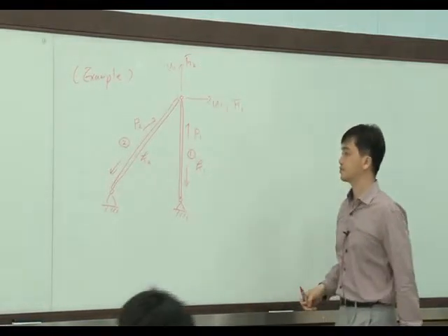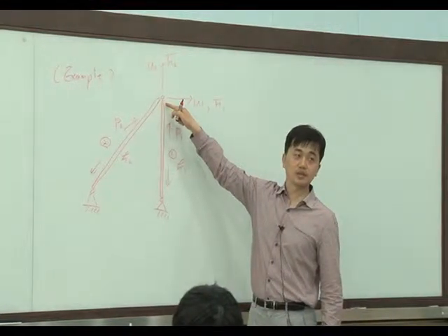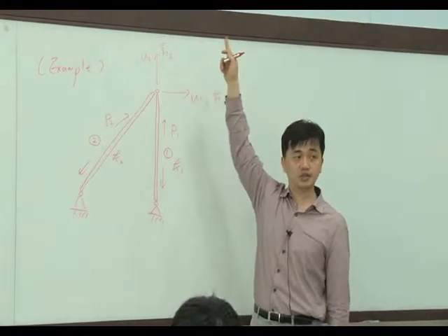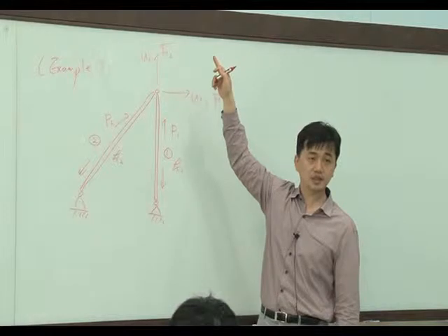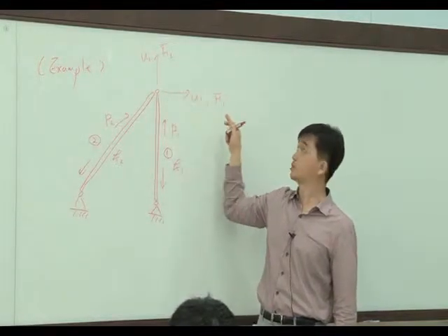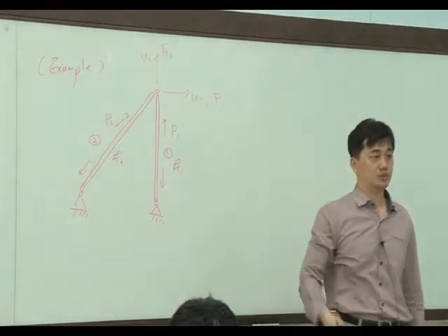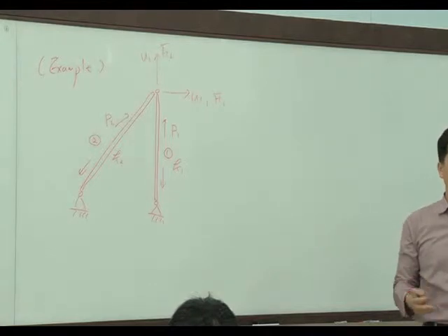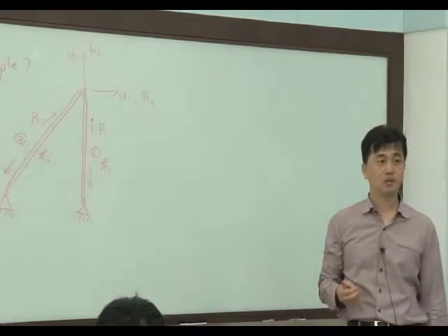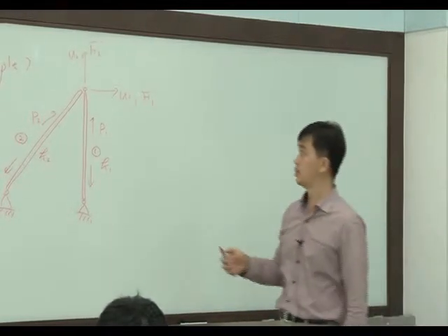So at this point it can move in two ways, in two directions: the X direction and the Y direction, right? And at this point, we can apply two different loads, F1 and F2. Then we can express all the possible displacements and forces applied. In a truss structure, force can be applied only on the pin.